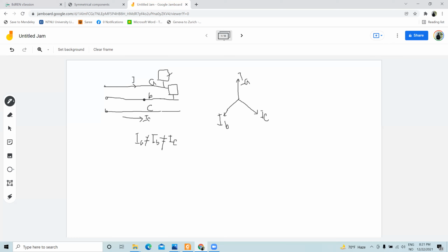If you go to IUT, for instance, if you stand on the first floor in the first academic building, on level one, you will see that there is a box just near the stairs, and from there you can see the three-phase voltage readings. You will see that the three-phase voltages are more or less very close to each other. They are not exactly the same, but very close. So if they are balanced, we can analyze only a single phase and solve the problems very easily.